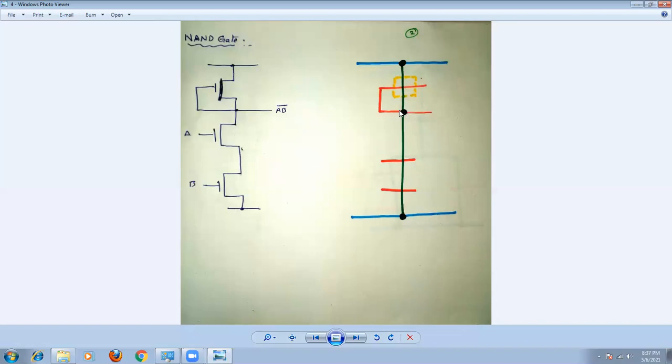So this is the buried contact or butting contact. The butting contact is shown in brown color. Remember these are the points; take a red color and extend to this one. So not only the extension, this point will be connected to the output terminal. It may be a diffusion layer in green color, or metal one, or polysilicon, right?